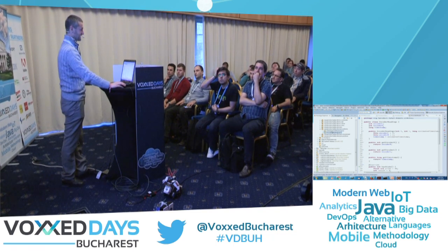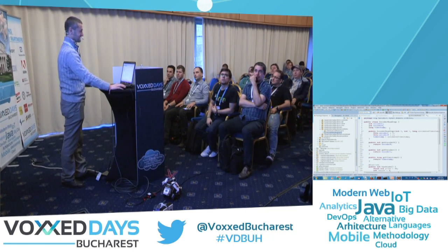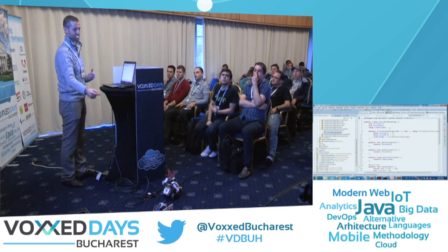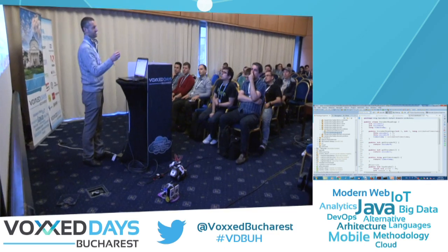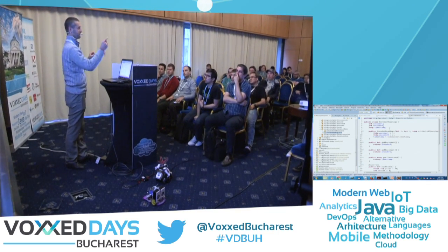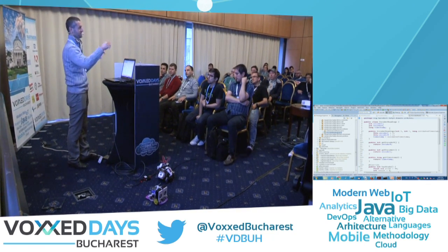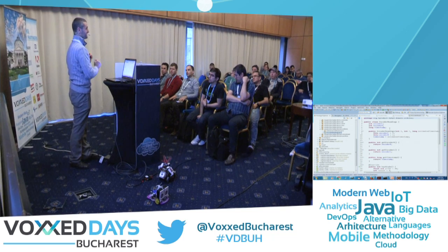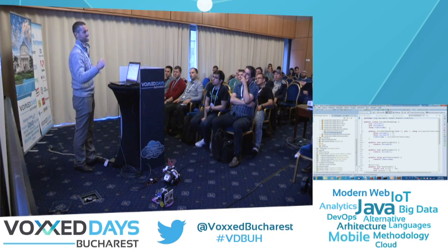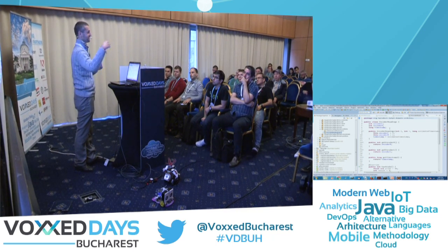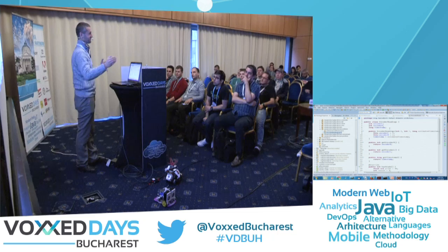Next one. It comes with Arduino Leonardo because it is a very easy way to interface your Raspberry Pi with Arduino in 5 volts. Your Raspberry Pi is in 3.3 volts, Arduino is in 5 volts. If you have sensors in 5 volts, you cannot connect them to the Raspberry Pi directly. You have to use some level shifter, or even better, offload all the processing to a real-time dedicated controller like Arduino Leonardo.